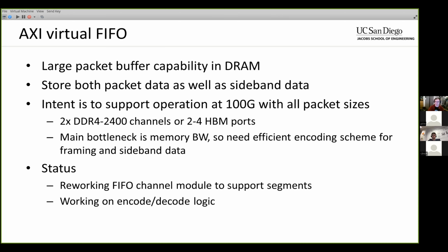This is one of those things where, on the first pass, you think you know how you're going to put the pieces together, and then you realize that maybe that first idea wasn't so great. So initially I built the FIFO channel module to just have a single AXI stream connection. You can just pass data into it, it puts it in the memory, takes it back out, and then gives it to you over AXI stream again.